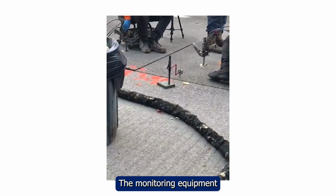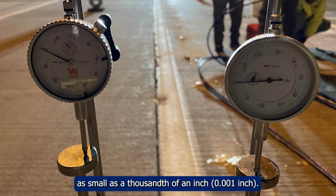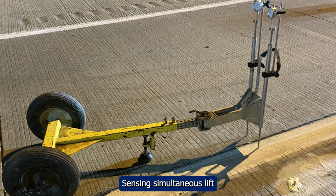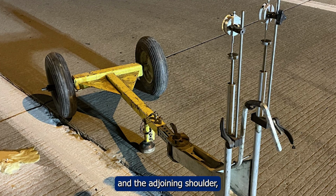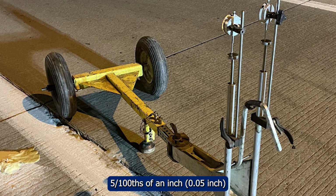The monitoring equipment must be capable of detecting slab movement as small as 1/1000th of an inch, sensing simultaneous lift at the pavement edge or any two adjacent slab corners and the adjoining shoulder. Any upward movement of the slab exceeding 5/100ths of an inch is not permitted for slab stabilization. Slab jacking under Section 681 is to be used for raising slabs to the correct elevation.